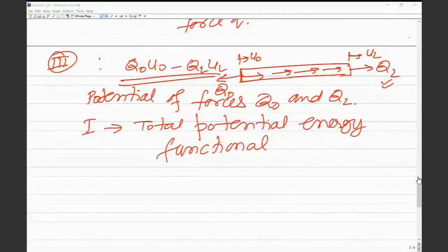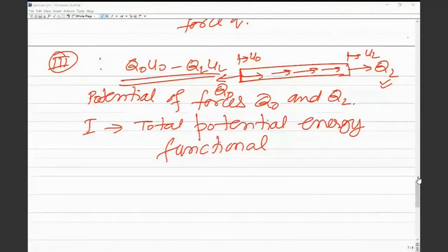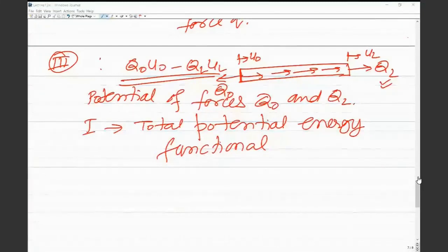Your secondary variable is a function of the primary variable, but what is specified is only the secondary variable. So the temperature will be unknown, and your heat flux would be a function of temperature there. So it has to be taken as a function of temperature, and then you solve the problem. The procedure would still be the same.